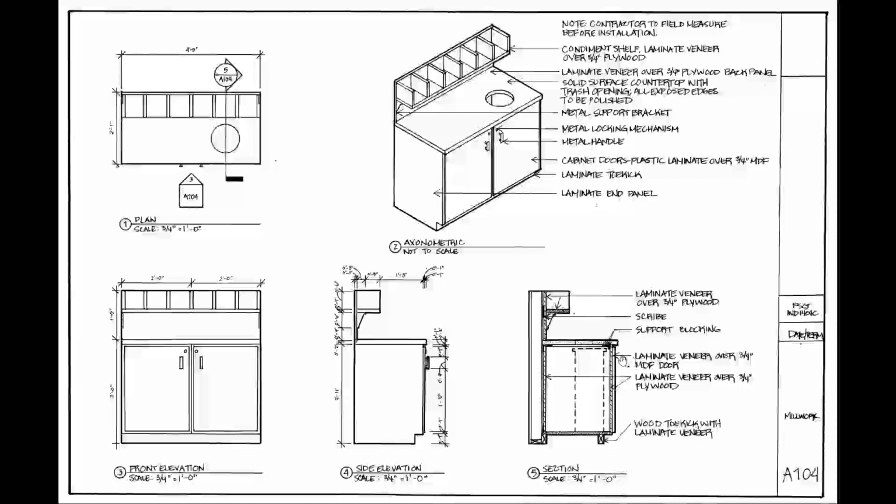We see the slice through the door, because we would also slice through the door here. We do not see knobs, because you can see where this slice is right here. We're slicing and looking this way, and the knobs are right there, so you would not see knobs. That's why you don't see them here. We see the texture indicating the countertop, and it's stippled in.